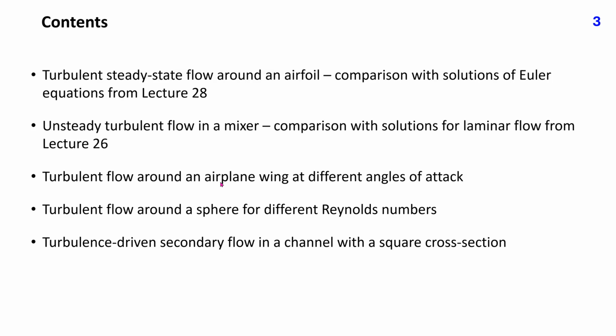The flow is unsteady, and the unsteadiness is imposed by the rotational motion of the impeller. Here we have to assume that ensemble averaging is performed, with one blade passing period being one member of the ensemble. If LES cannot be afforded, an unsteady RANS approach can be used in such cases.